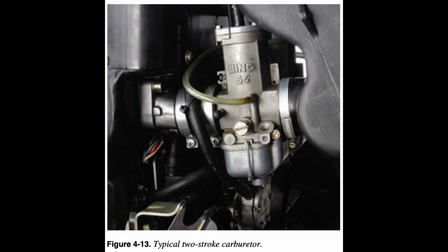The pilot must be aware of the jetting for the machine to adjust the mixture. Consult your POH for specific procedures for setting jets at different density altitudes. 4-stroke mixture settings. 4-stroke engines typically have automatic mixture control for higher altitudes or a mixture control that can be operated by the pilot.